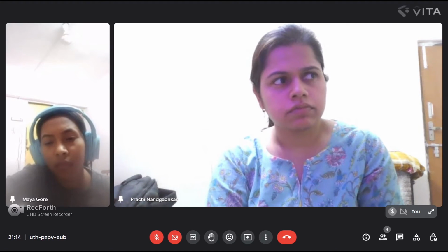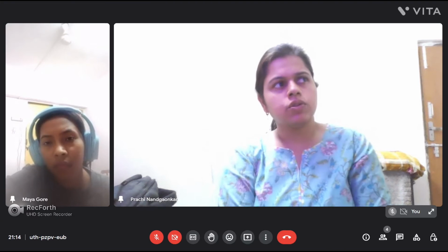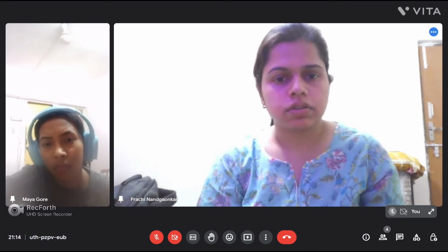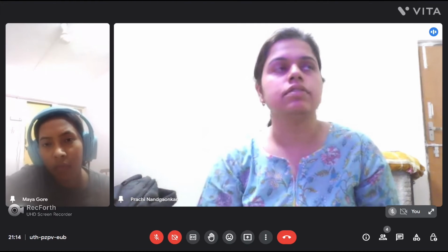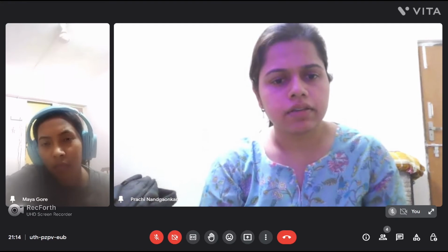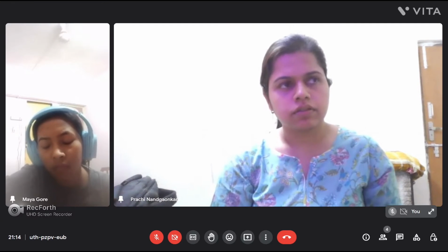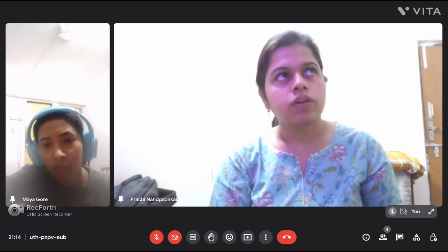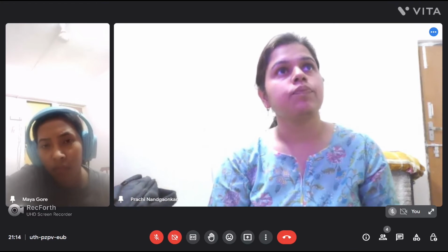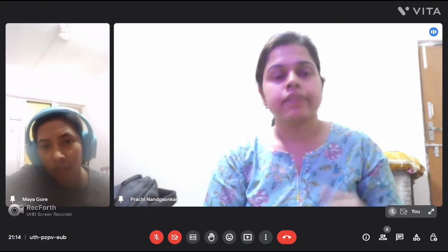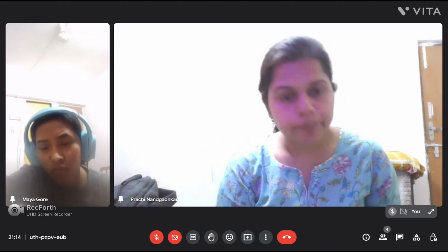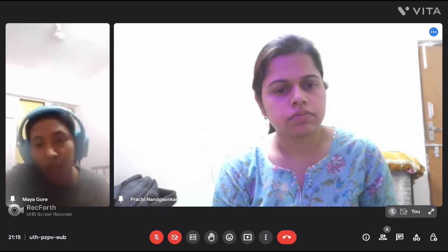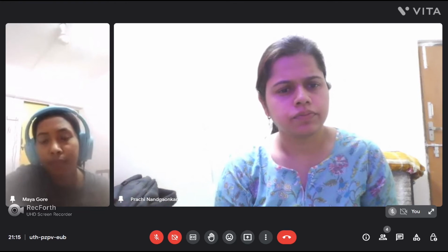To implement n cross 1 mux, how many 2:1 mux do we need? To implement n cross 1, there is 2 to the power n. Okay, let's make it simple. To implement a 4 to 1 mux, how many 2 to 1 mux do we need? It's 3, sir. To implement 8, how many do we need? 4, 5, 6, 7. Yeah. Wait. So basically it is n minus 1. Yeah, right, sir. Good.